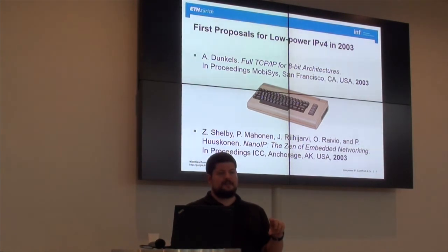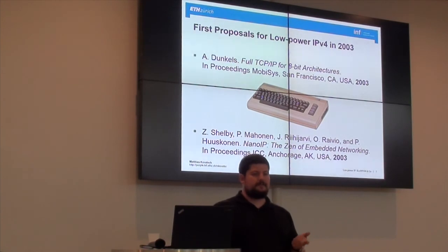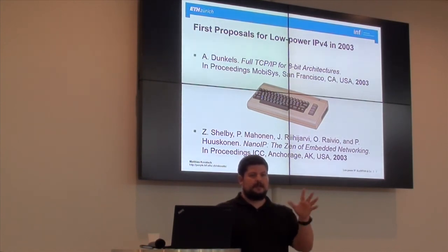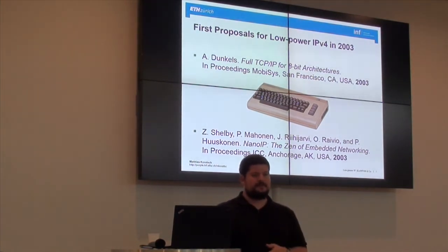Those devices will probably need these crypto accelerators for DTLS handshakes. But yeah, that's where it starts. Probably the rollout will be a bit larger devices with, I don't know, 64K RAM and 200 kilobytes ROM. Then the CoAP application takes only 10 kilobytes. Yeah, so the protocol stack with every feature is currently at roughly 10 kilobytes. But that's already with a lot of convenience glue code and so on.